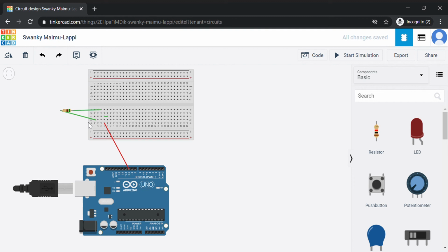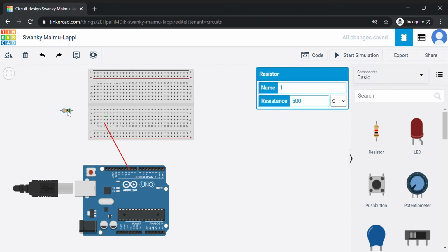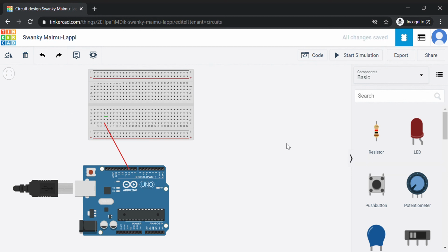You don't technically need to use the breadboard if it's exceptionally confusing, although we find it's helpful to get a sense of how everything connects, but you could just connect everything purely with wires here in TinkerCad. If I want to delete something, you can use the delete key on your keyboard like I've been doing, or once you've clicked on it, you can go up to this garbage can, click it, and it will disappear.